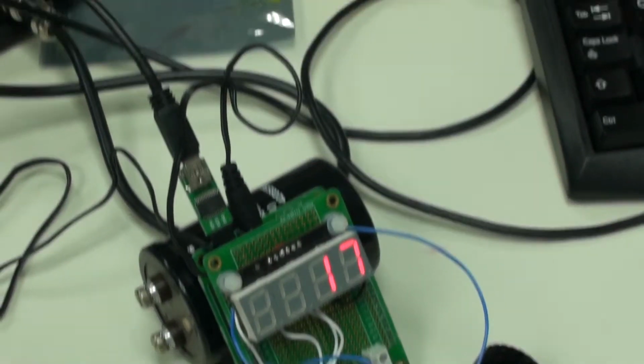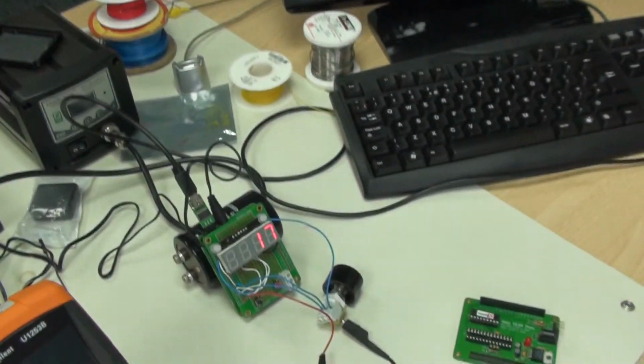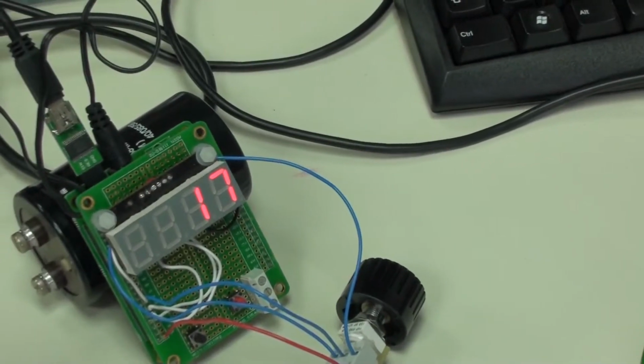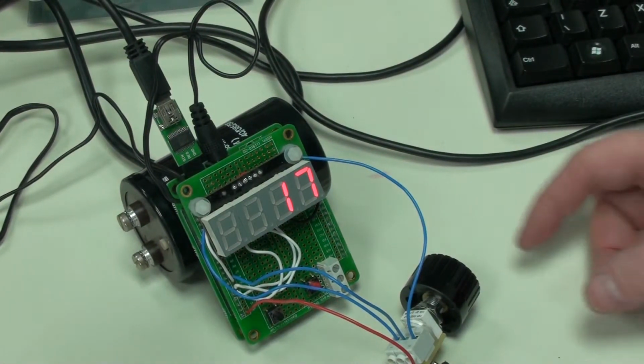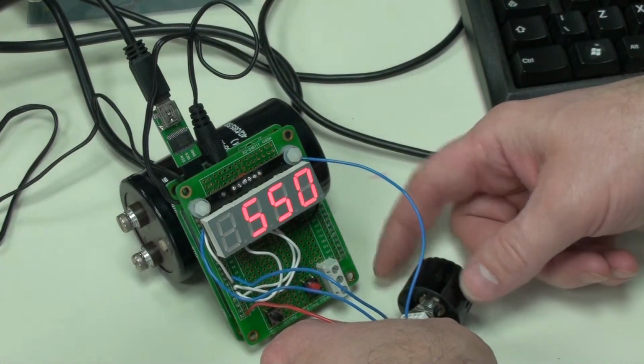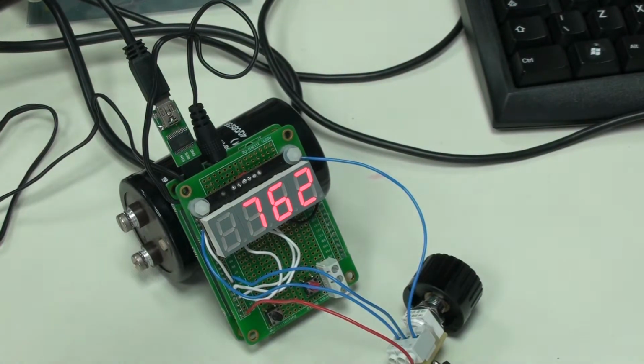The downside of this is that because each time you call that command it's taking 64 readings, it's now increased the time for the conversion to 7.1 milliseconds. That may or may not be acceptable depending on your application, and if the conversion time's not suitable, that's when you'd use the circular averaging system, because that way you'll still get the smooth result, but it'll be giving you a result every so many microseconds as opposed to milliseconds.